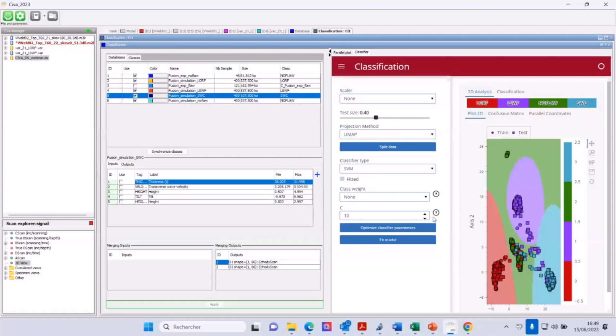So it's a 2D analysis here, and you see that you have dot points that are the train data and the squares that are the tests. And you can see here that you have different zones just to see if we are quite good or not that good with color codes with the different classes that I defined, lack of root fusion, lack of sidewall fusion, no flow, and the last SWC flow. And you can see the different points.